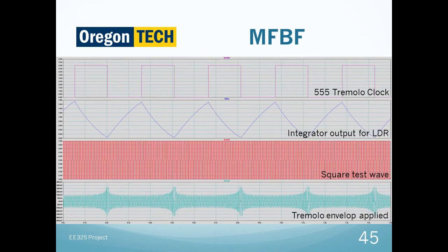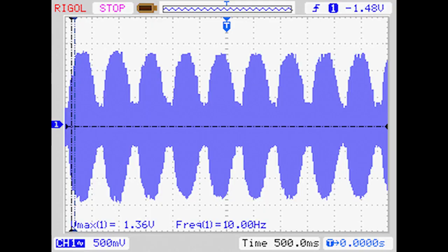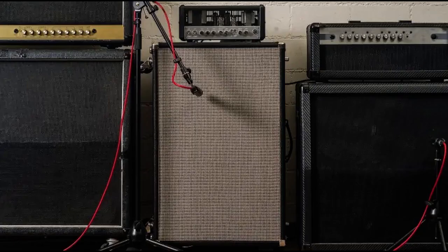Due to the 50 Hz to 70 kHz center frequency sweep, the envelope applied to the carrier wave is not linear. A restriction in time-varying resistance, and consequent restriction in center frequency sweep, would result in the envelope being applied more evenly over the range of the tones the guitar is able to produce.